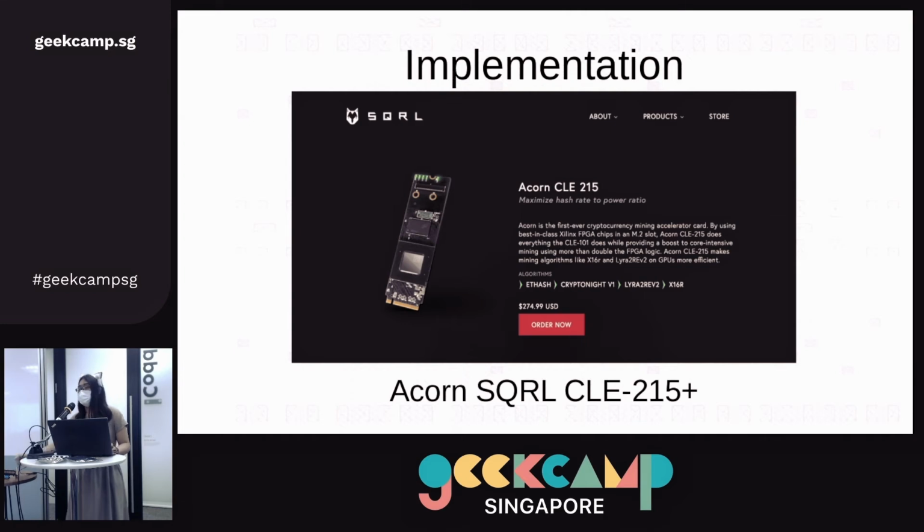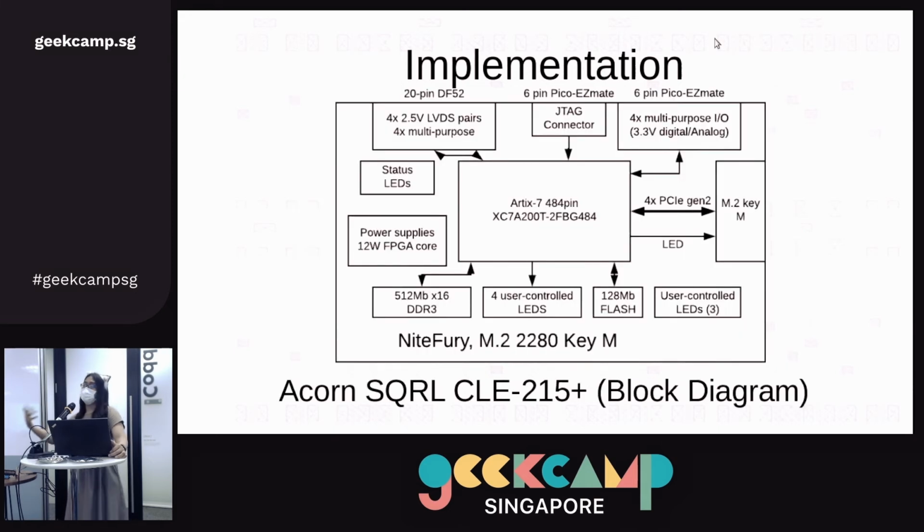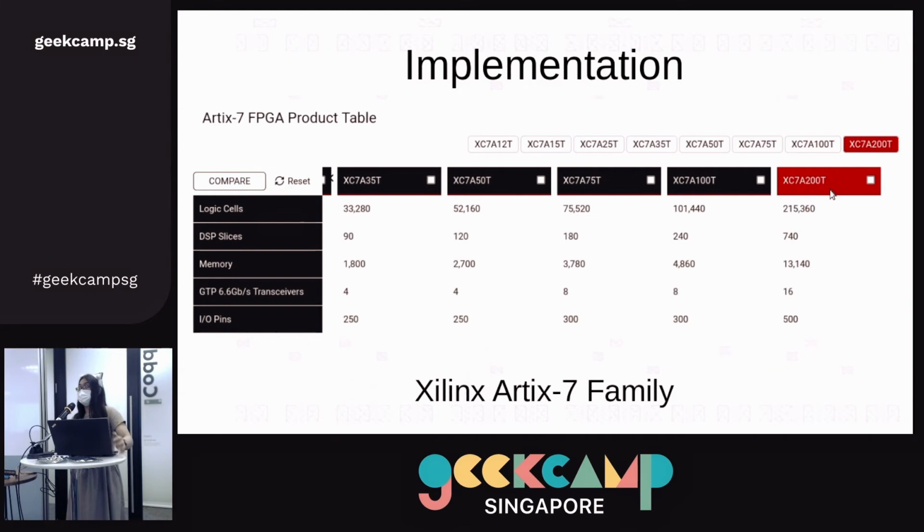And this is the block diagram of the device itself. You have an Artix 7, actually 7A200T, and for a price like $120 US, it's interesting, because what you're effectively getting is the highest end Artix 7 in this module right here, with 200,000 logic cells. This is the highest spec part in the Artix 7 series family they can get.